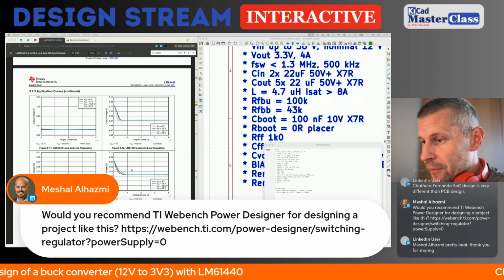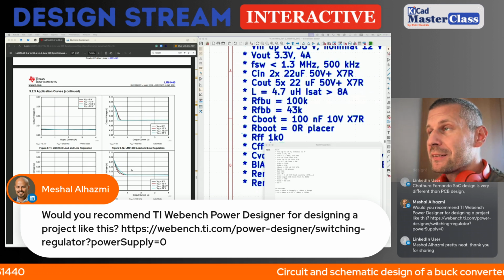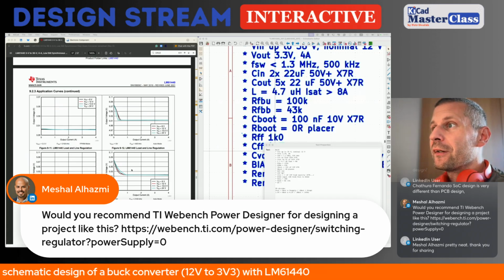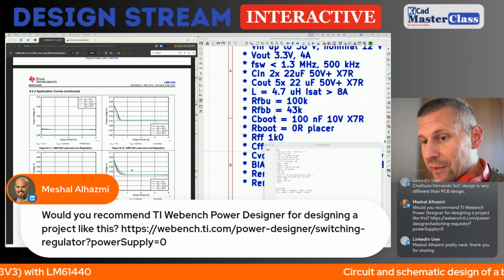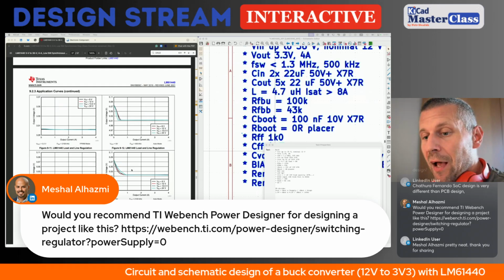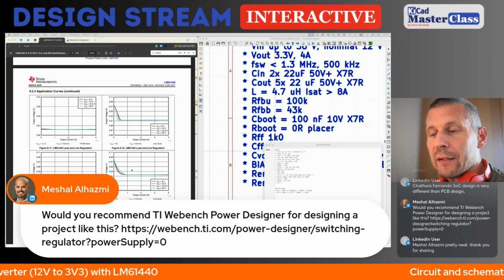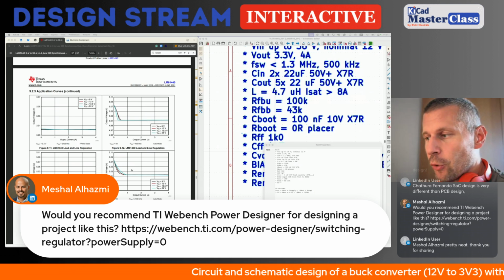Yeah, and if you are asking me, would I recommend? Yes, I would, but as a second step. The first step should be going through the datasheet, checking formulas, doing at least rough calculations, and then verifying your calculations with the Power Designer, with the WEBENCH. The thing is that sometimes even WEBENCH or similar designers can be wrong, and you don't want to be wrong. So use it as a checker for your calculations.